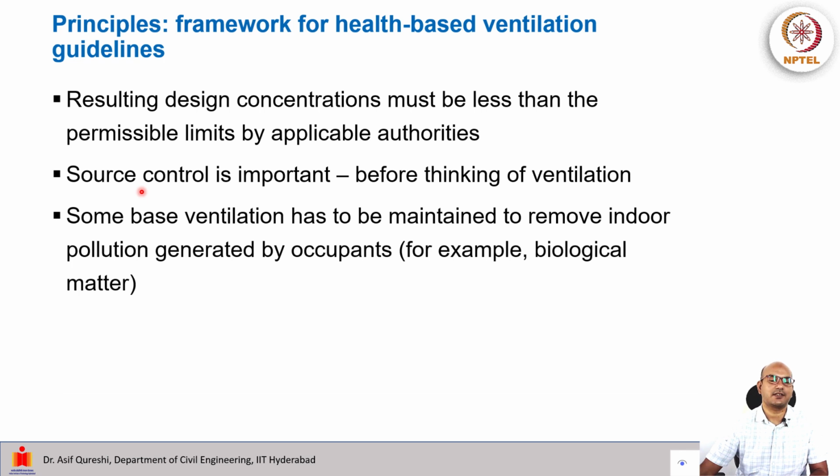Of course, we are thinking of ventilation as an amelioration, as a mitigation factor. The most important thing actually remains source control, because if the source becomes cleaner, then the requirements of ventilation can be relaxed. So source control is very important before even thinking about ventilation.